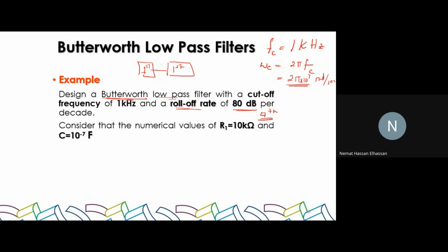If you want to create a fourth order filter, what you can do is take 2 second order filter circuits and then connect them in series. So what you'll end up with is a fourth order filter. Make sense? So now let's keep that in mind.